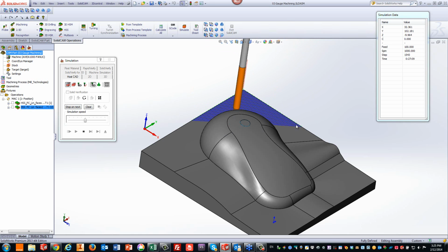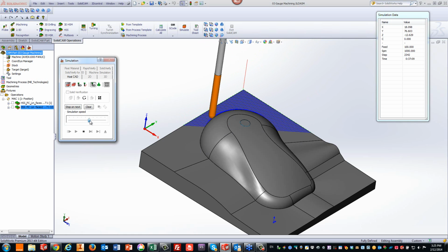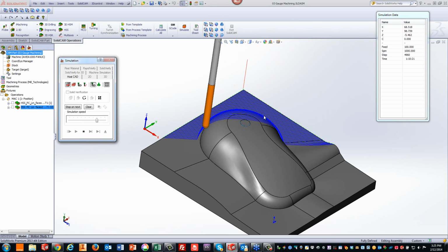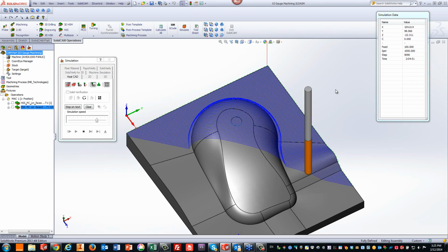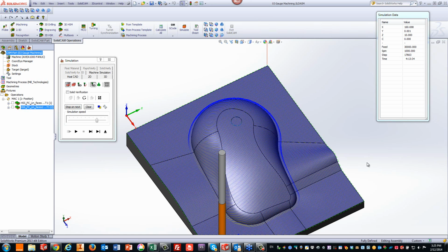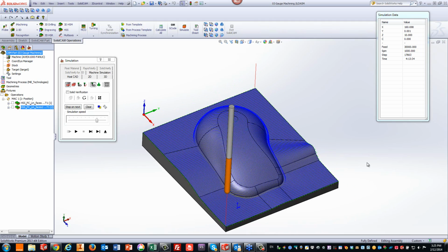But it's taking the path of the actual surface on the bottom, but on top of this surface instead. So the result is you're getting that really nice, straight linear toolpath without any kind of jumping, just going over this area itself, giving you that really nice toolpath you're looking for in this particular case.